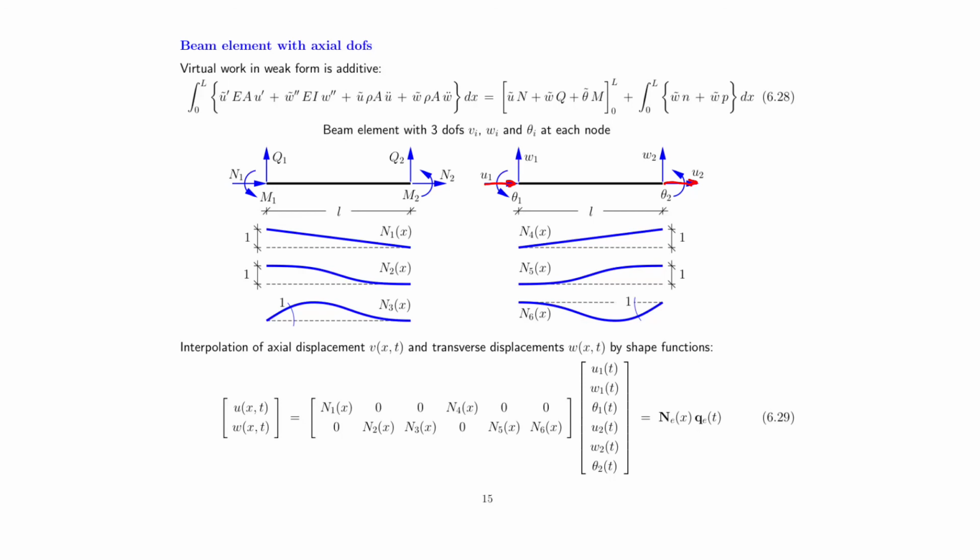And as we remember from the cable element, that requires the first order derivatives of the corresponding displacement, in this case the horizontal displacement u, and then instead of the tension force H, you should simply have the axial stiffness EA. For the inertia term, we will have the corresponding displacement and acceleration, and then the mass per unit length, which, by the way, is the same for the beam element as in the transverse problem, where we also have rho multiplied by A.